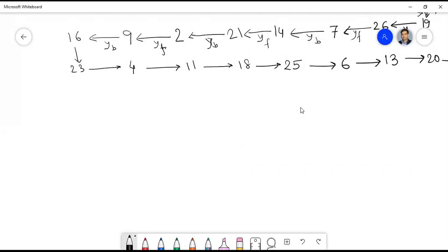The expression of voltage, you know, for total is ZA by A, P phi and n, where ZA is the total number of conductors, A is the number of parallel paths, P is the number of poles in the machine, phi is the flux per pole, and small n is the speed in revolutions per second.